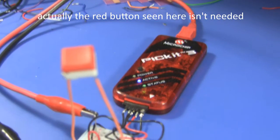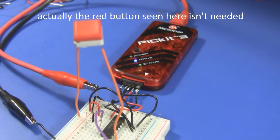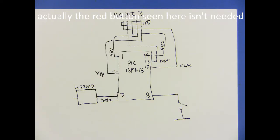And then I additionally have connections to the PICkit 3 programmer on the breadboard there, and you can also see a button, and this is how I have it connected. Just the usual 5 connections to the PICkit 3 programmer, and one output for the LED drive, and I'm powering it from a separate 5V power supply, as the PICkit 3 probably can't provide enough power to drive the LEDs if they're all turned on at once.